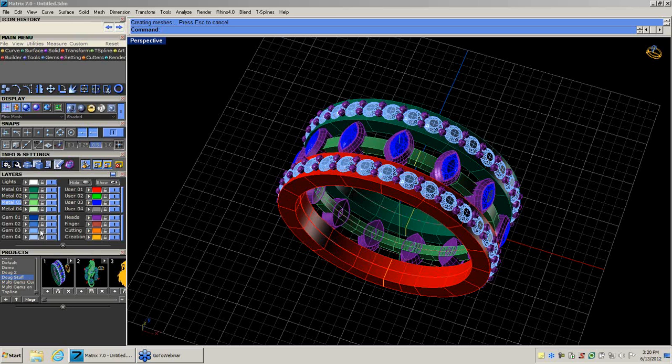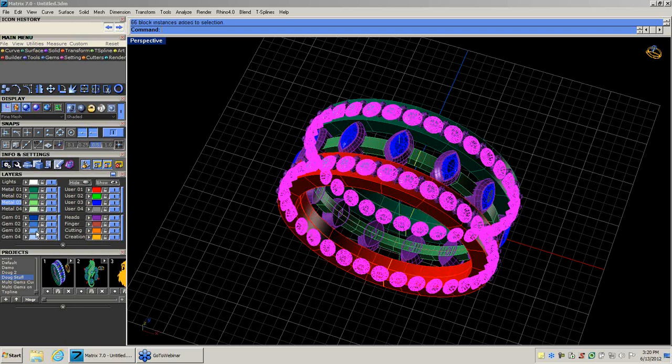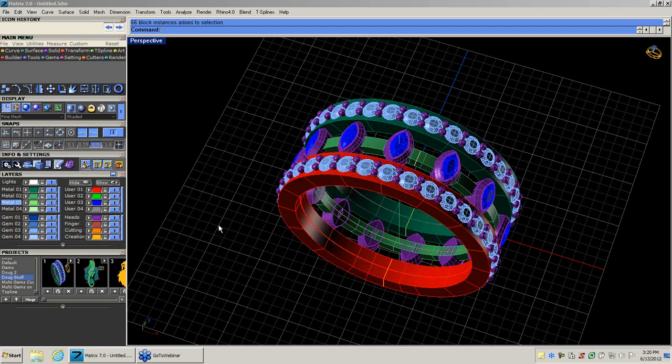We've also made it so that if you right-click on any layer, you can grab everything on that layer. So if you're trying to move something, render, or change something, sometimes it's a lot easier to just right-click on the color than to sit here and hold down Shift and try to grab whatever it is you're trying to select.